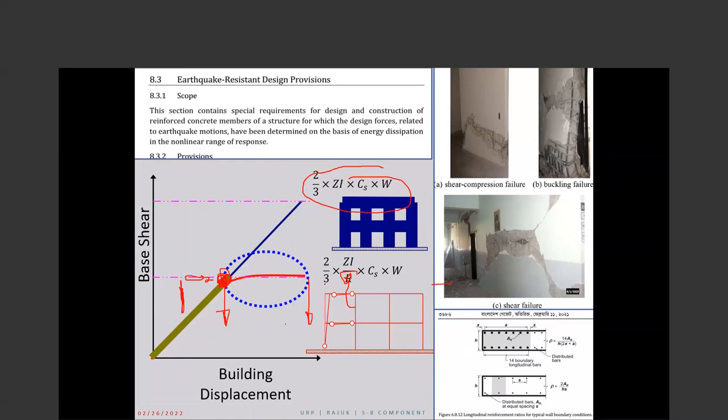And because of that, we always multiply the displacement that we get from SAP, ETABS based on the system that we are using. But we are putting a smaller strength in the elements. We know that it causes damage.